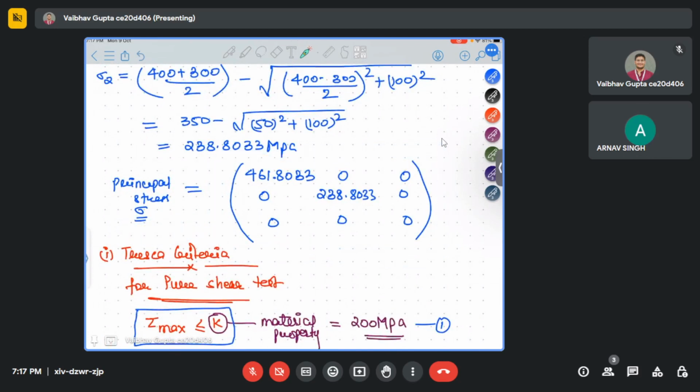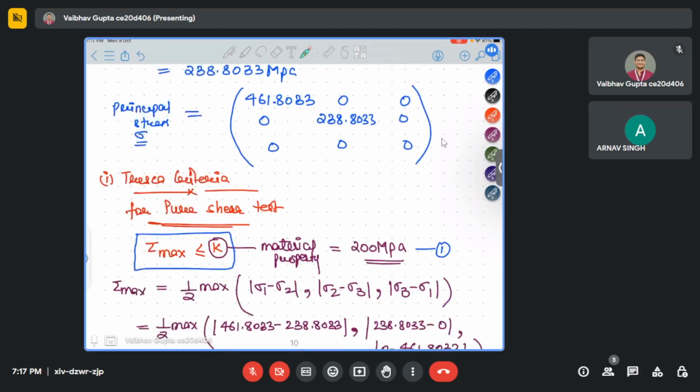Now in the question they will ask you as per which criteria this material will fail or not. In this question I have used two criteria: first Tresca, second von Mises. The question says the material has a yield stress in the pure shear test of 200 MPa.